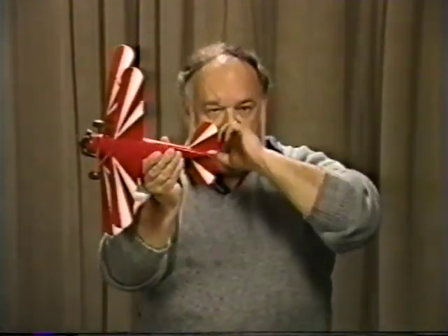We have another situation you have to think about, and that is stick-free and stick-fixed stability. When you're flying along with the airplane and you take your hands off of everything, feet and hands off, the rudder will just free float. It will just sit there, and if the airplane yaws, the rudder will just sort of trail along with it. When you're flying along, the ailerons will just sit there and float behind it. Your elevator will do the same thing.